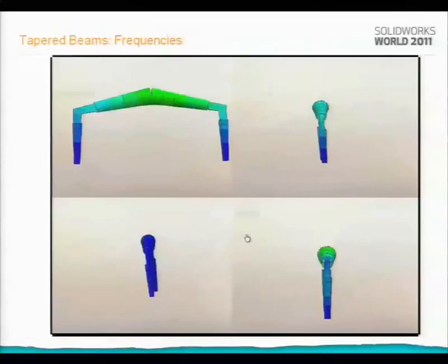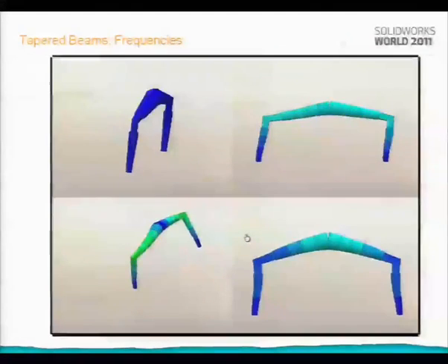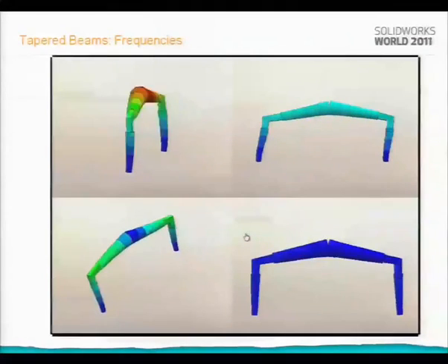The first column is the first and the third mode. They are out of plane. So if I fix the out-of-plane mode, I will get only the second mode. So this is a way that the engineer could do it. For example, if I have equipment acting in the first mode at 19 hertz, I can fix only this plane, and I go to the second natural frequency, right? Only fixing this mode.